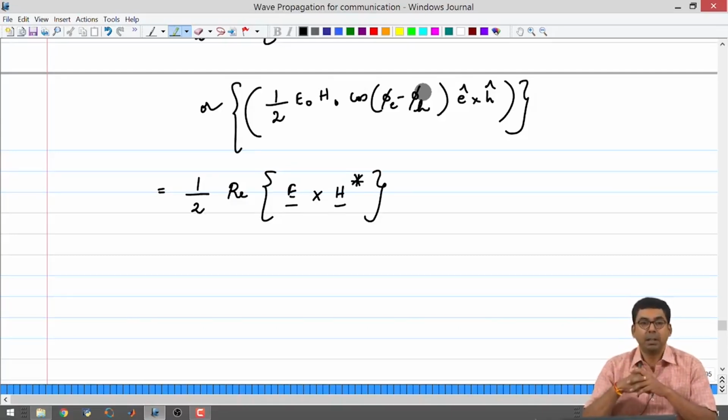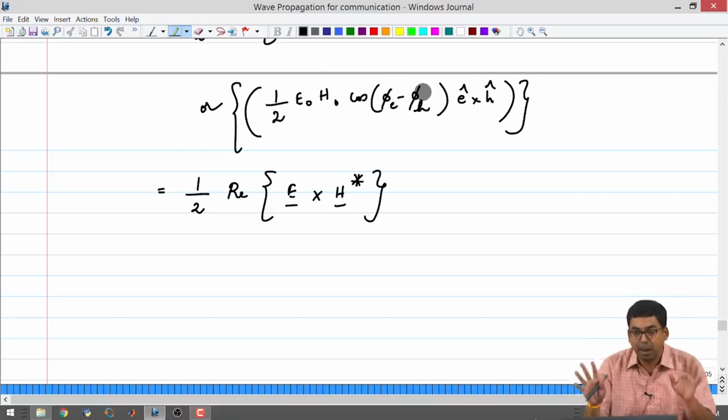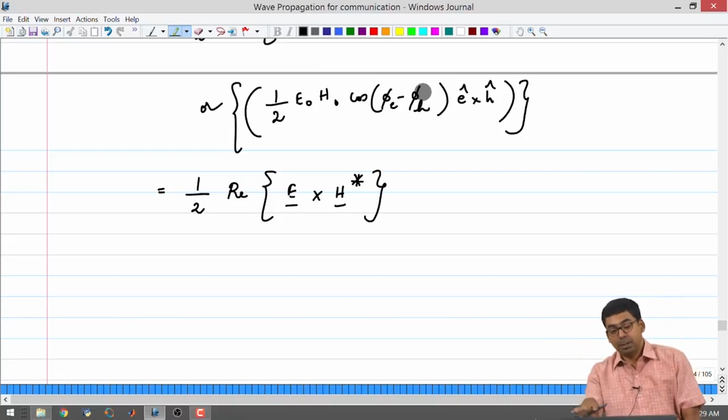In the same way, in a capacitor you have C dV/dt as your I, which means that voltage and current are out of phase by 90 degrees, or current will lead the voltage by 90 degrees. Again, you cannot transfer power to a capacitor, or power cannot be dissipated by the capacitor. So, the equivalent can happen here also.